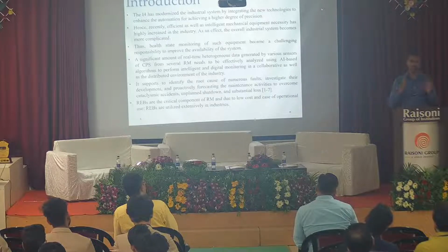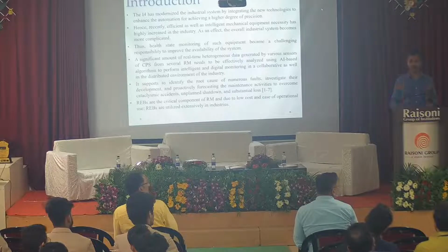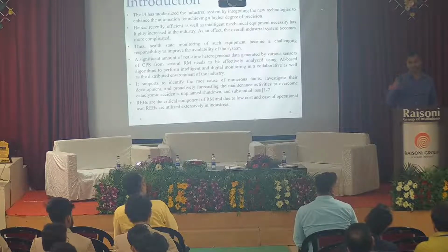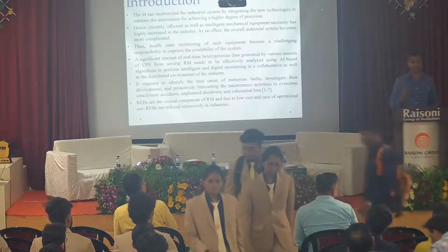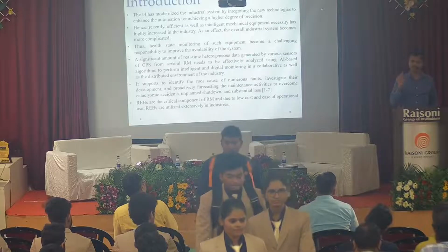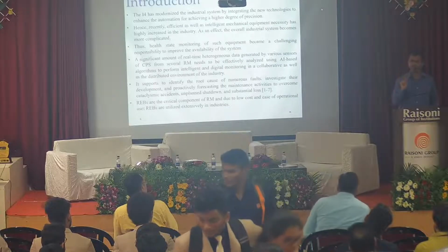Not only that, the wheel position is also fixed. There are 4 wheels only, 2 at the front and 2 at the back. We don't have more than 4, and the position is also fixed. We want relative motion. The bearing gives the relative motion for the movement, and the bearings there run continuously. If you change the design of the coach even minutely, the bearing will fail.